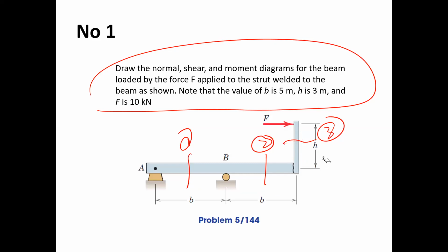Yeah. Wait, sir, I have another question. For this homework question, it was only to find the internal force systems for the beam, right? The horizontal. But when you cut at the second section between B and the right end, if you took the right part of your cut, would you also have to find the moment at the welded part, or could you? Nope. You don't have to. What you can do is like this. You can draw it just this way. Okay, something like this.